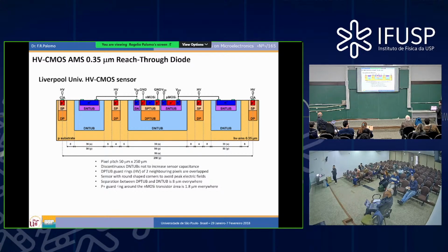So this is one of the first simulations of monolithic detectors, where the point in those years was to ensure the stability of the biasing of the diodes inside the substrate without affecting the electronics on top. The electronics here is just for simulation, to know about the influence of the electronics on the general biasing.